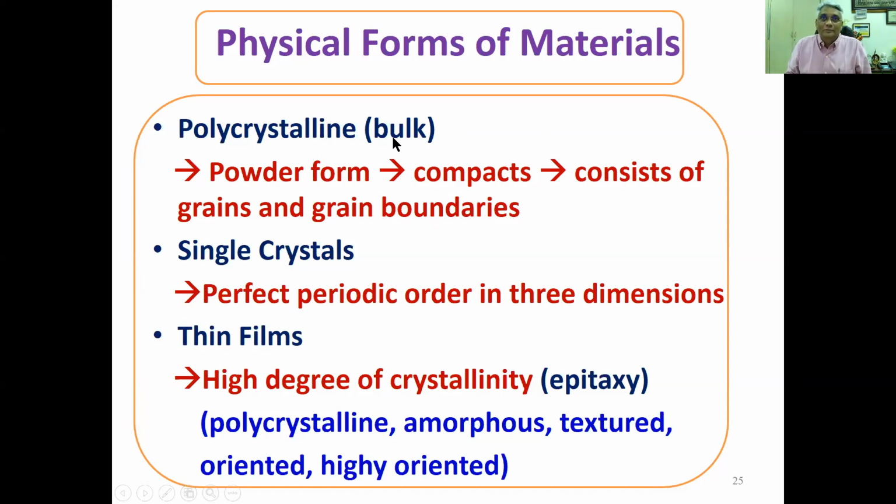Same is the case with single crystals. So the processes that are used to get thin films, polycrystals, and single crystals are all different. Then the definition of a single crystal is, well, I can convert this polycrystalline material into a single crystal if I make the polycrystalline powder or bulk through the process of single crystal growth. Right? There again, like PVD and CVD techniques, you have several single crystal growth techniques available. One famous technique is called the Bridgman technique. Another famous technique is called the Czochralski technique. It's the Czochralski technique that is used to grow these large balls of silicon crystals from which silicon wafers are cut for device fabrication. You have flux growth method, you have hydrothermal method, your Czochralski method. There are so many single crystal growth methods.